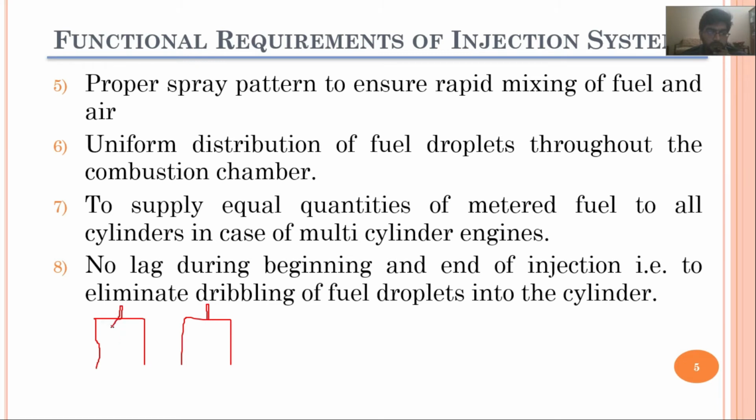One is this spray pattern and the other one is this spray pattern. So the second spray pattern is basically covering a larger area, and thus it will result in making a more homogeneous mixture, a mixture which is closer to homogeneous, you can say, because neither of them would make a proper homogeneous mixture since the fuel is injected afterwards.